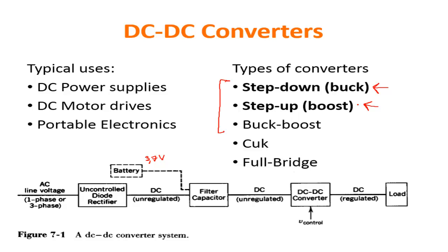And with a buck-boost converter, the third option, you are able to change the sign of the supply voltage. For example, if you need -9 volts for the programming operation of a flash memory, you need the buck-boost in order to obtain -9 from 3.7 volts. You need to invert the voltage.